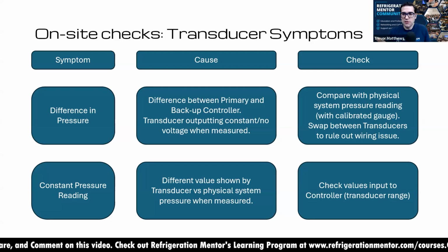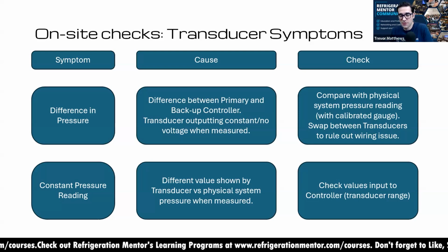And then like you just said, most of the systems you see now are 60 bar, right? 800 and some PSI standstill pressure. All the ones here in Canada, I don't know many that are that high. There are some, but most of them are 40 bar systems, standstill pressure. So depending on where you're at in the world, you really want to understand that specific system that you're working on. And that is key to your success, because I really try to teach technicians that they can go work in the UK, or Germany, or Australia. But it's understanding that system.